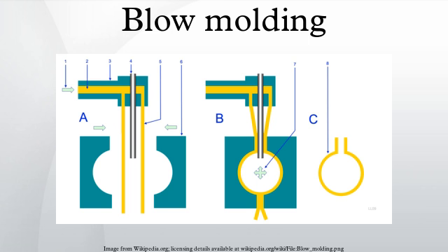In the ISB process, the preforms are heated above their glass transition temperature, then blown using high-pressure air into bottles using metal blow molds. The preform is always stretched with a core rod as part of the process. Advantages: very high volumes are produced. Little restriction on bottle design. Preforms can be sold as a completed item for a third party to blow. Disadvantages: high capital cost. Floor space required is high. Only suits round bottles.